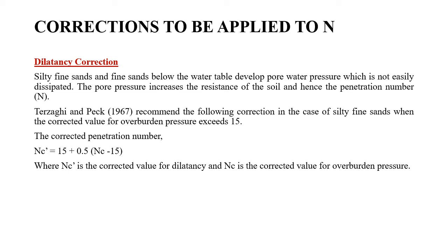Now, the best example for dilatancy is when you step on the beach sand. What really happens is the sand immediately under your feet gets compressed or compacted, and then you can see that the sand around your feet gets dried up very quickly. Okay, so what really happens is that when you're compressing the sand under your feet, the water from the sand around your foot area will move into the compacted sand under your feet and fill up the spaces. Okay, so this is what really happens in dilatancy. There is an expansion in volume which is happening. Okay, and this is prominently seen in silty fine sands and fine sands.